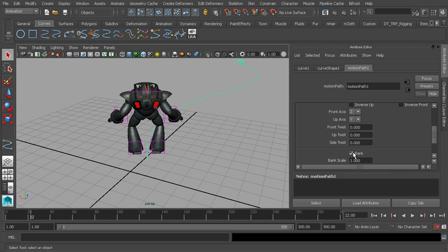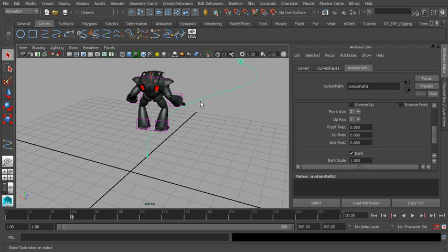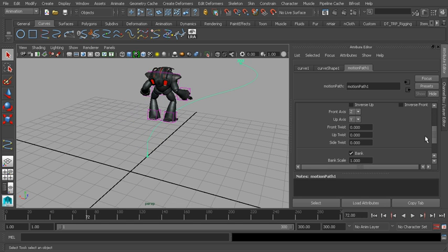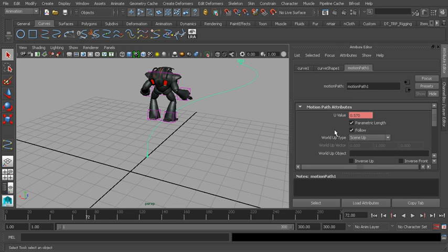We could also animate a bank, which is a way of having the object naturally twist and tilt along our curve. And then if we'd like to push it a step further, take a look at these parameters we have. Our front twist, I'll hold down control and drag with the left mouse button to interactively change this parameter. You'll see that we're able to adjust the twist along our path to offset the animation if we would like. How cool is that? So we essentially have XYZ control here. Cool. So that's basically a look at our settings.